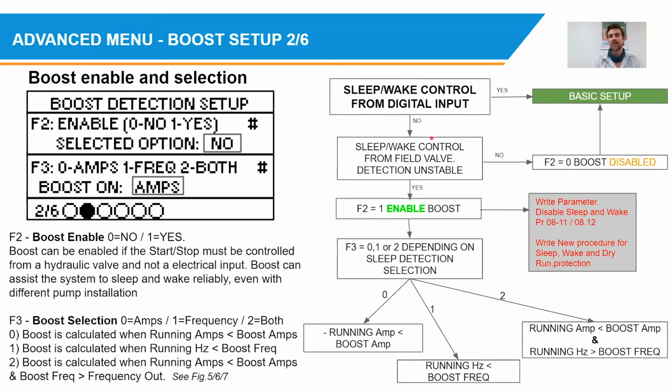All right. If your sleep and wake control to turn the pump off and to turn the pump on is expected to happen from a field valve, from you closing a tap and opening a tap, you would like the system to completely shut down and you'd like the system to completely start up again. If that is the case, we should consider enabling the boost option.